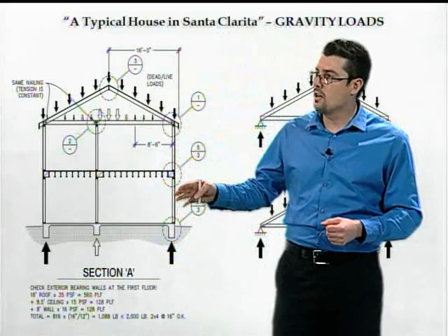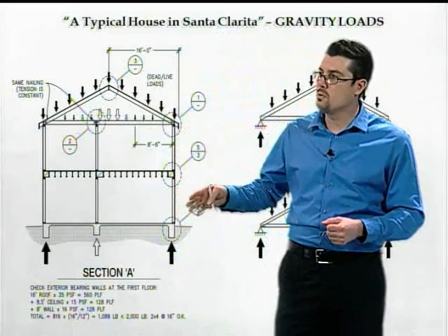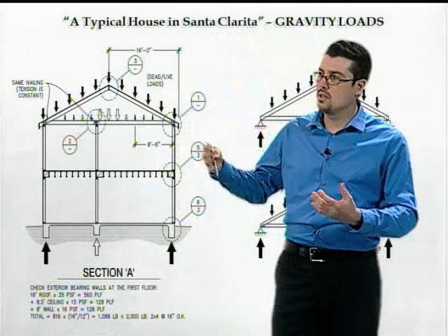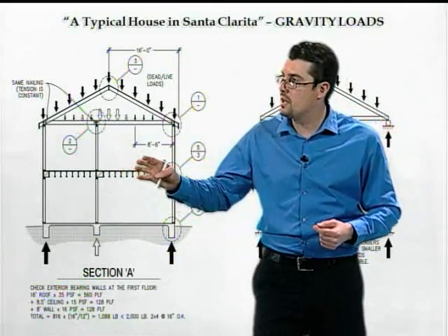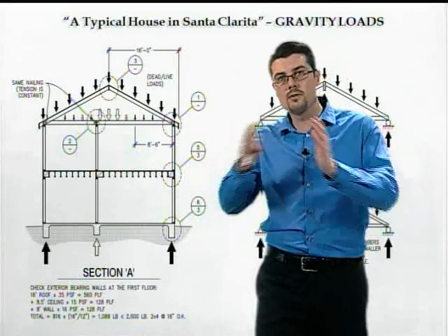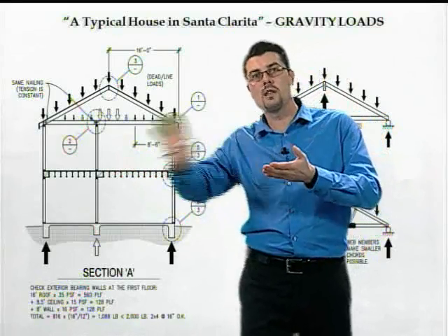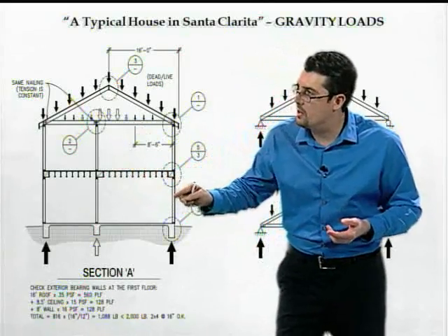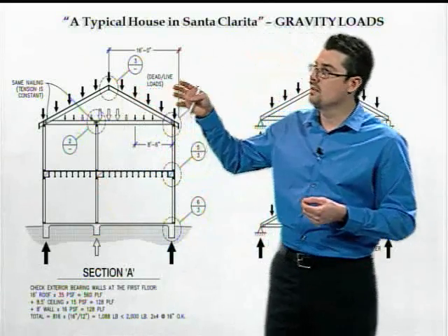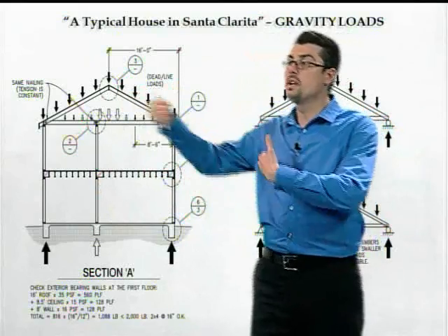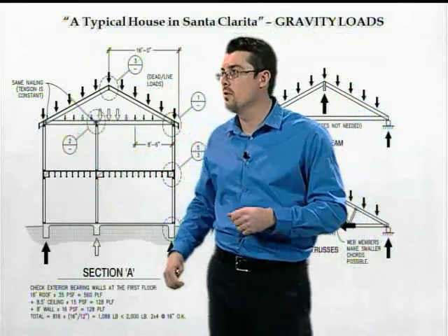This is something we would check on every house, especially two-story homes. Make sure that the bearing walls calculate for the load. But that's exactly how we design it. Now the floor joists are spanning the other direction. The floor joists aren't loading those walls. They're spanning the other way. So this wall here would not carry any floor load. It would just carry the roof and ceiling loads. The walls beyond would carry the floors.